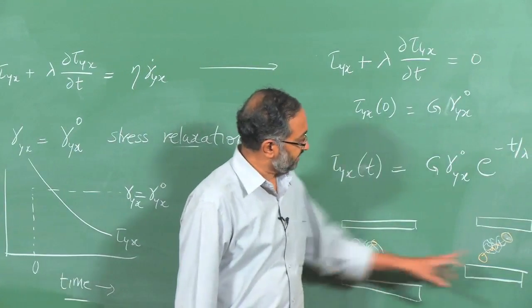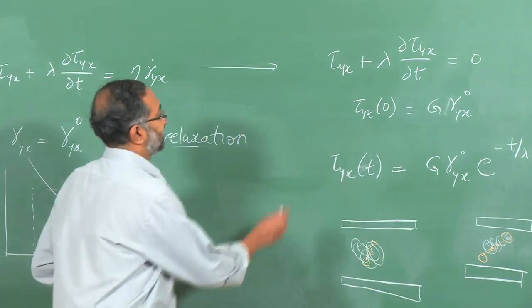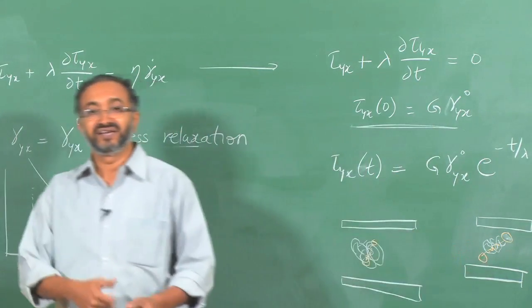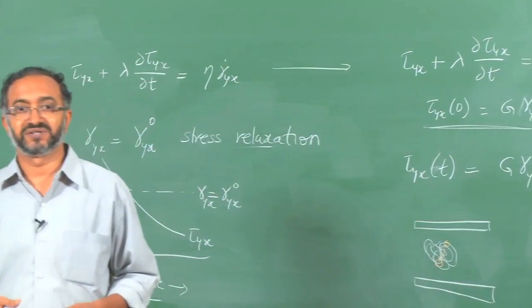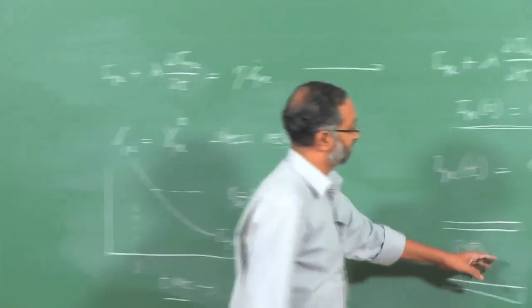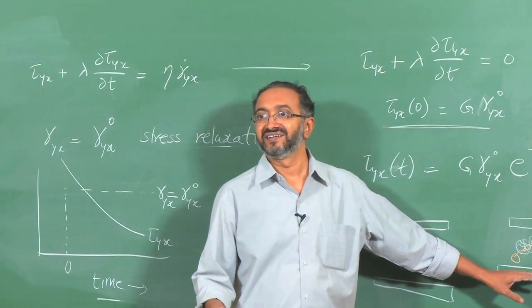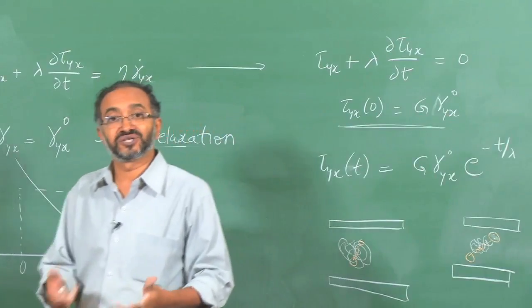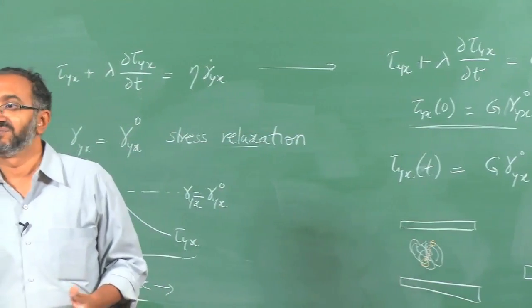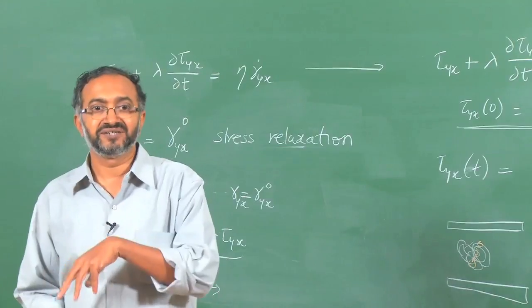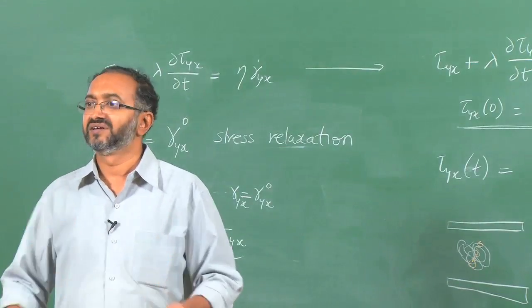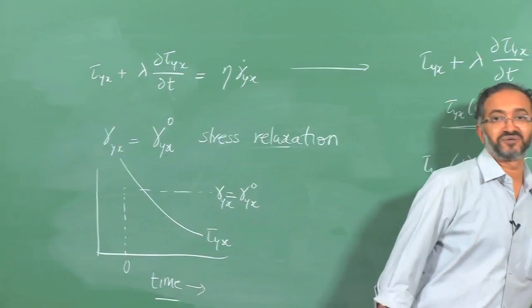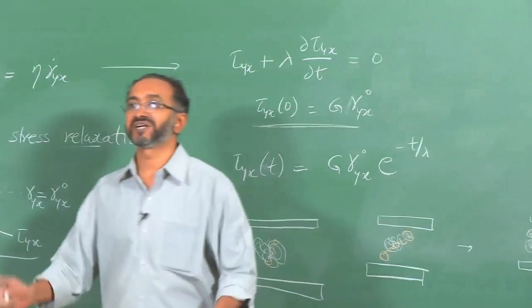So, at time t is equal to 0 is this stress that we talked about, right. So, therefore, any viscoelastic material initially will show an elastic response. So, if let us say I do the same experiment and observe it for a microsecond, then I will see only a response like this, and then I will say, oh, macromolecular solution is almost elastic. But if I do the same experiment over seconds or minutes, then I will say that, oh, the energy is all dissipated, the molecule actually got deformed, but it came back to equilibrium state, and therefore it dissipated the energy away.